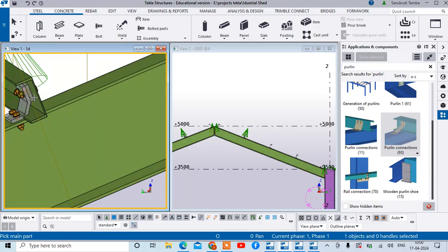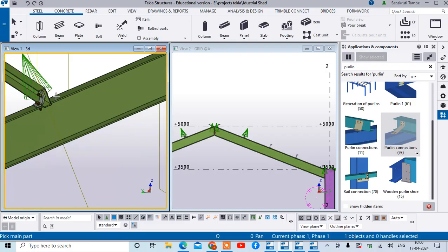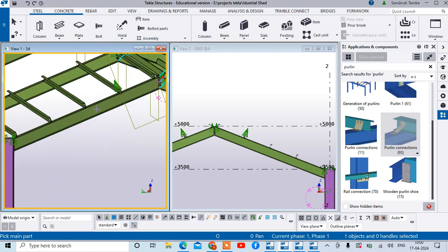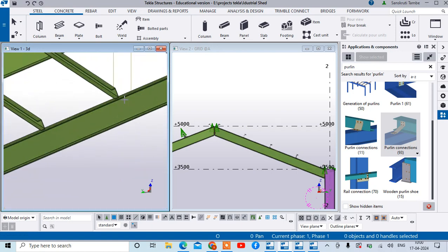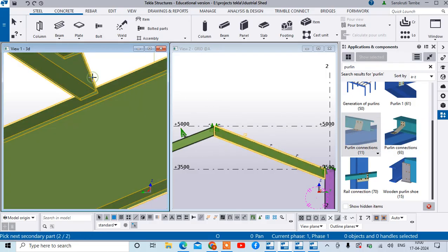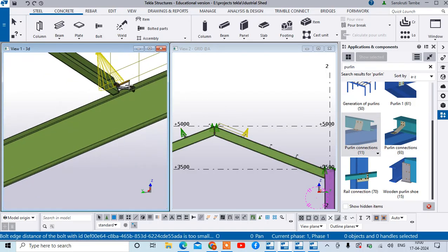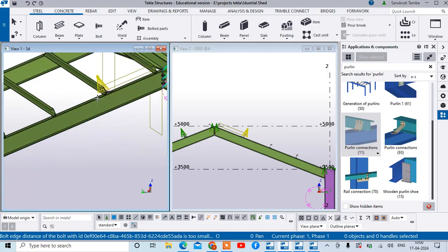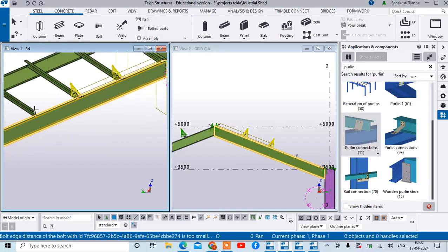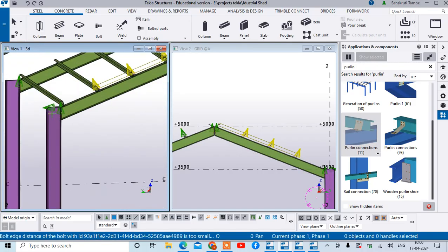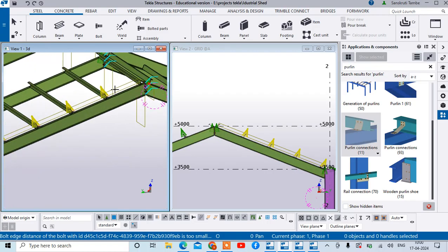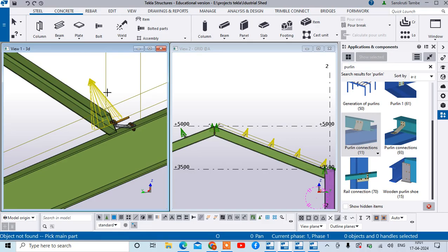Okay, now here if you want you can give it on another side also. Just undo this, and for this side I will take this connection, main part, secondary part and middle mouse button. Then here again main part, secondary part, middle mouse button. But now you can see here this yellow color mark.